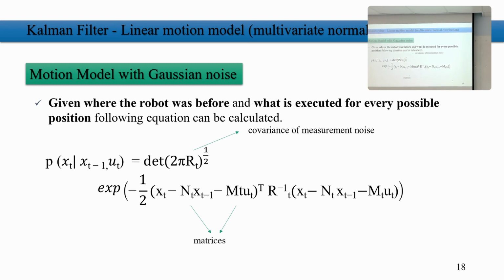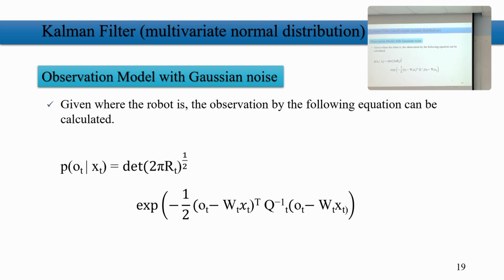To do this, we said we have a motion model with Gaussian noise. It means that we are bringing in our motion model, where the robot is moving based on the control commands in the environment, and we also want to consider the noise that we have there. So we've written this rule. Then the same thing with the same combination: last week we discussed that we can write the probability of the observation given xt with this term over here.